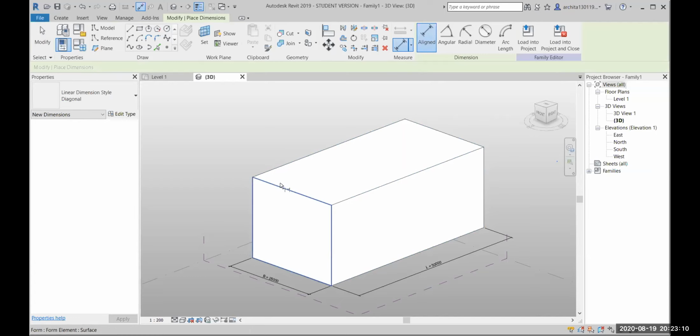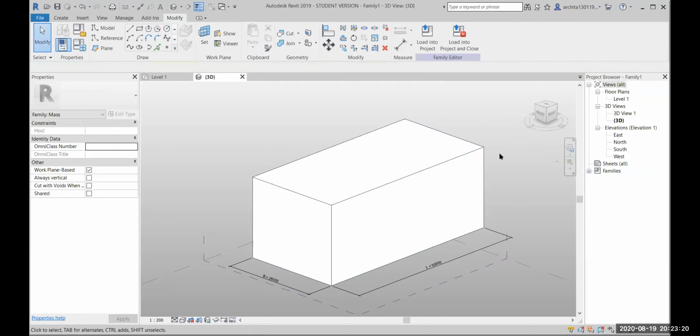No, ma'am. While creating a parameter, I'm getting an error: there is a circular chain of references among the highlighted elements. Why does this error come? Because either you have the same error I mentioned earlier: if you have named H as 12 and then you name L as 3H or something like that, then that's an error in the formula.